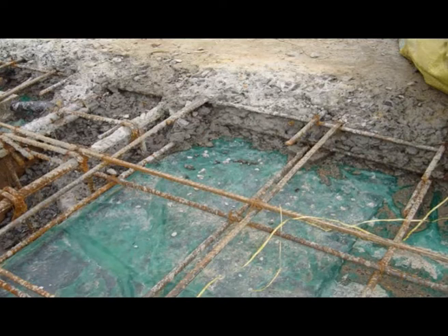Now one more thing is the form, because at that time the concrete is only a butter-like mix. So only with proper support will it work. Otherwise, what will happen? Because we get the strength as you already know, we require 28 days, which is called curing. Another important part is the support, which should be given proper care, because there will be leakage during casting of concrete, and if it becomes a loophole, then obviously it will fall and the whole construction will suffer. That's the care for the support system.